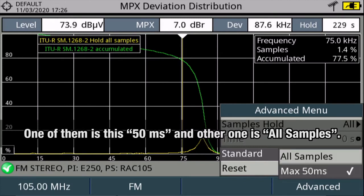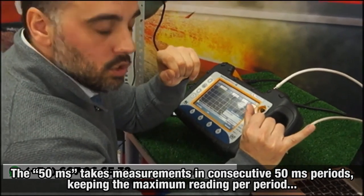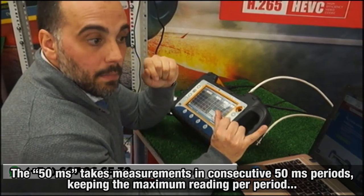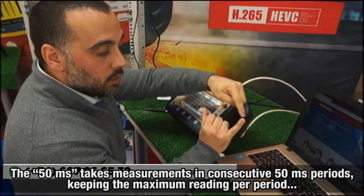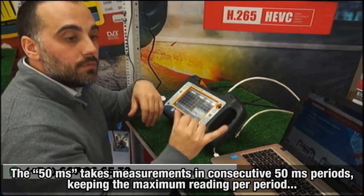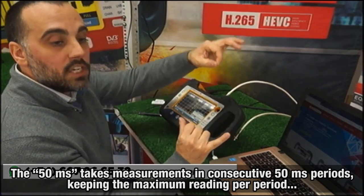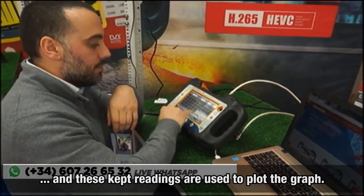I'll explain what we're doing when we calculate with this max 50 milliseconds. We take a period of 50 milliseconds, and we take several measurements over the FM MPX deviation during that period. When the period is over, we keep the maximum of those readings. Then we do it again, and so on over consecutive periods of 50 milliseconds, and over each of those periods, we keep the maximum reading. And with all those readings that we keep, we plot this graph.